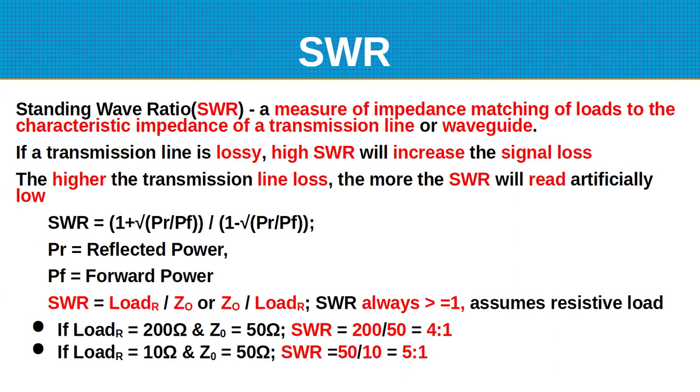The reason, if you think about it, I put 100 watts out into the feed line, and I have a 3 dB loss going to the antenna. That's not actually unusual. At the higher frequencies with a long piece of coax, like 100 feet, you could easily have 3 dB loss. So that means I'm only getting 50 watts at the antenna. If I had a perfect match, I wouldn't get a reflection, but I only have 50 watts at the antenna.